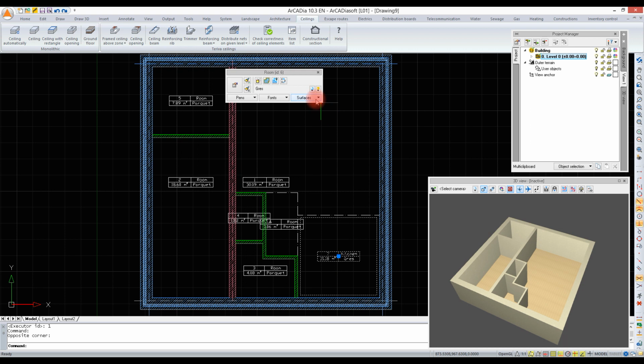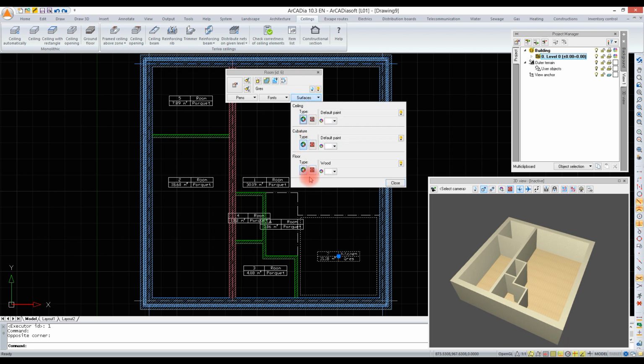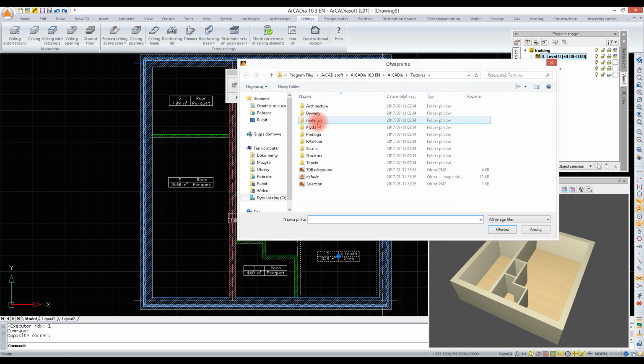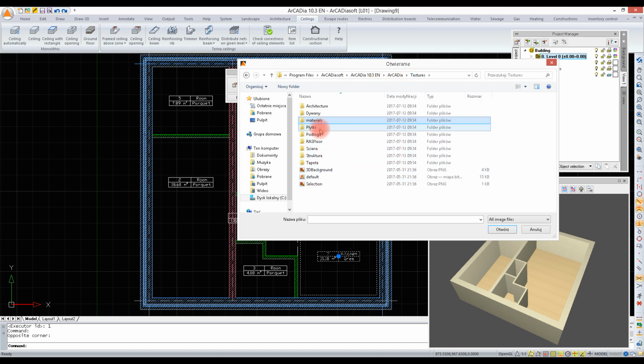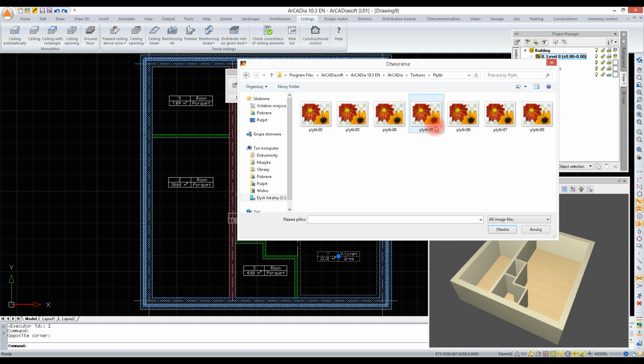To show another color scheme on the floor, it is enough to select the room and then select the texturing option by clicking the Surface button. We can select any texture from any place on the computer, but once it is set, we can't move it or modify its name because the program remembers the path to the selected file.